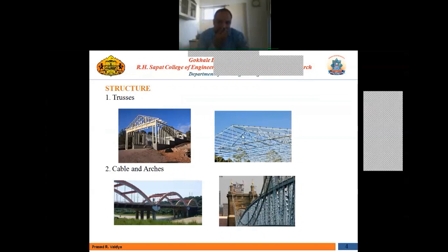Of course, you should have a triangulated geometry everywhere to behave like a truss type structure. But there are again constraints practically once you put the two bolts, because for analysis purposes we will be assuming that each joint is a pin joint or hinge joint, but once you put two bolts or two rivets, it may not be a purely hinge type or pin type behavior, right.